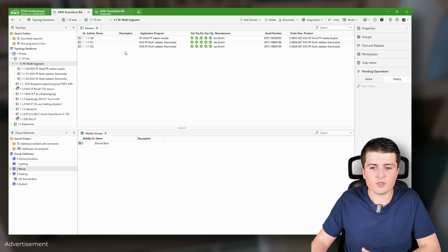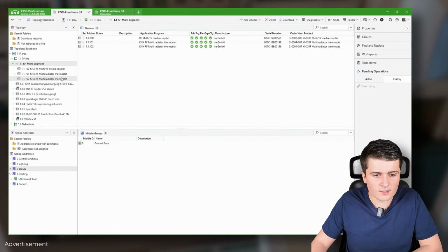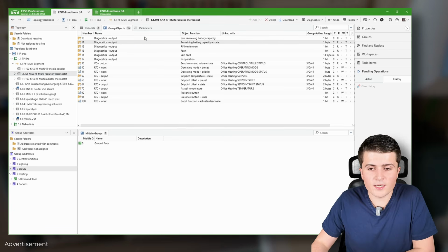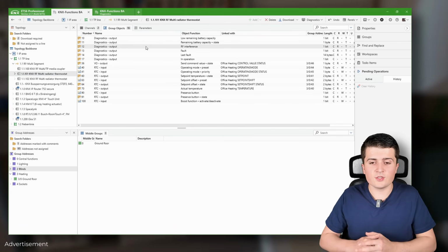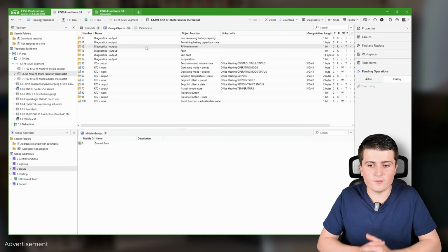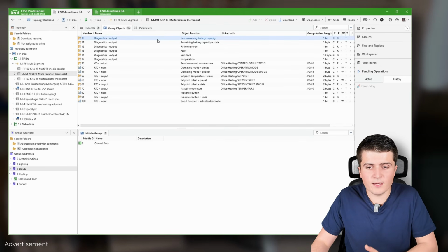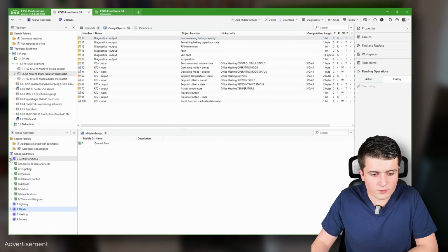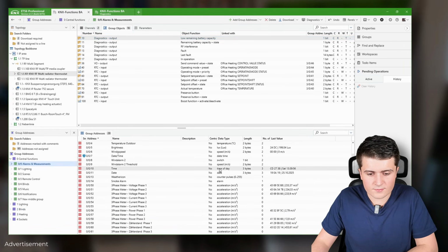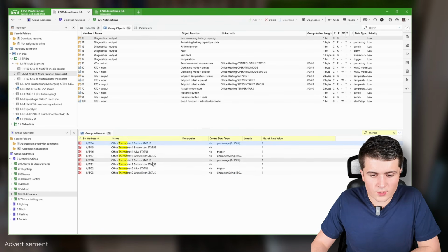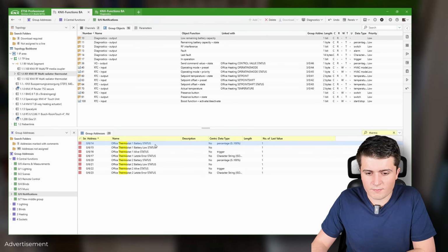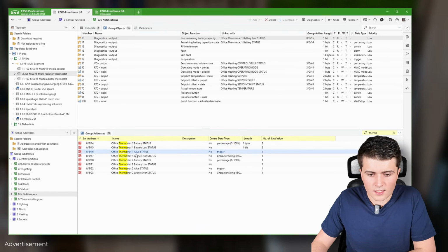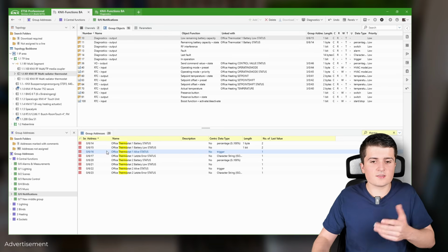Now with this running, let us jump back into our settings of the radiator thermostats, because I want to show you some additional functionalities. I now want to connect some additional diagnostic information, like, for example, the remaining battery capacity and the current fault state, and for that I have also already created some group addresses. So here you can see office thermostat 1 and 2. Here we have the current battery capacity, then battery low as an error message, then the keep alive group address,